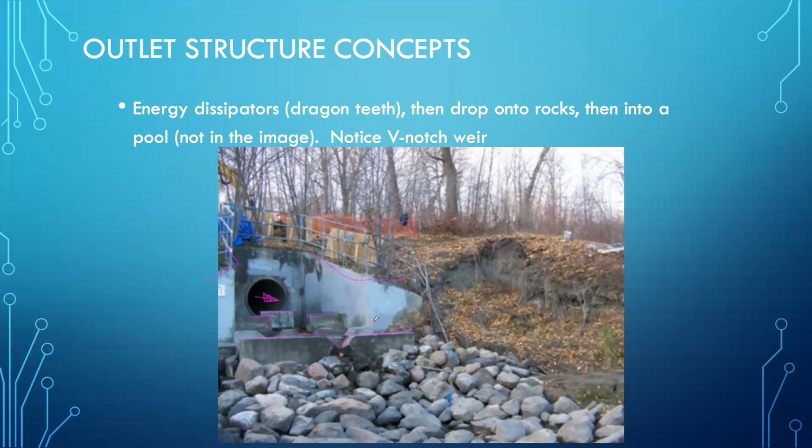And it appears that later on, a large pool formed during flows, and we got erosion in this area. And so a later project introduced these large rocks to help keep the soil in place. And from a design standpoint, something needs to be done with this portion where there's been mass wasting. And that arguably may not have anything to do with the outfall other than being located at a place where the outfall contributes to the existing stream and creates a gyre or a circulatory effect that slowly washes away this soil. So this is a pretty darn engineered outfall.